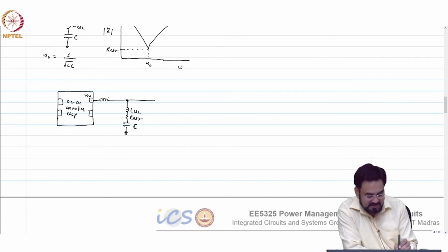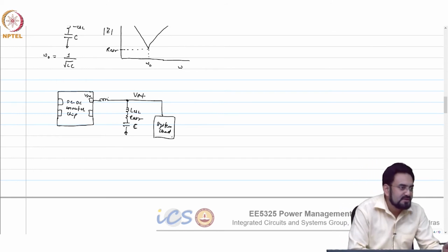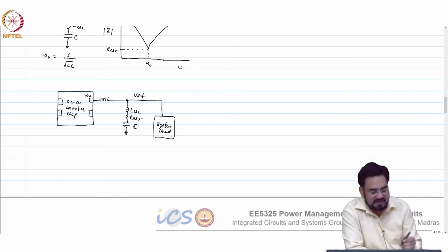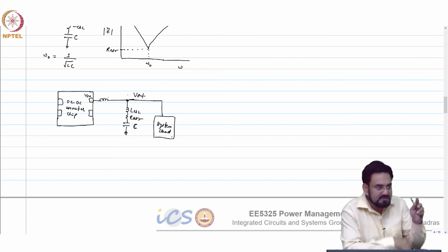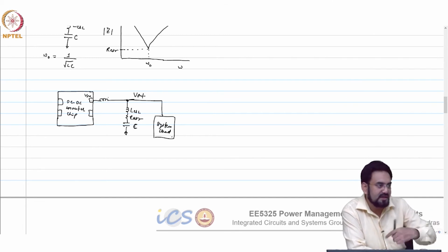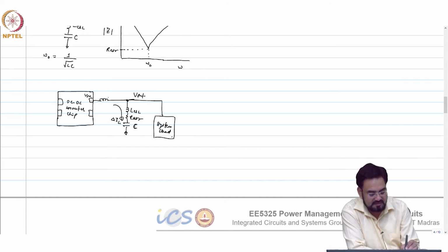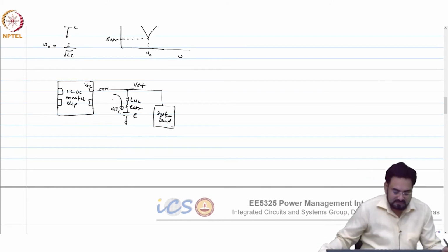When you are taking the load, let's say this is your system, the system load, and this is your V out. So when you are connecting the cap, you have to make sure this capacitor is closer to your system. That's the one thing you want to avoid, the R also. Wherever you are connecting V out, it will be placed close to this trace, so it will look more like a star connection, so that you get an effective cap. Your inductor ripple will go and get absorbed in the capacitor. So you don't want to have this large L in the inductor current or ripple current path. That portion you have to minimize, because this is your delta IL which is flowing into this, and that's why we try to reduce the inductance.